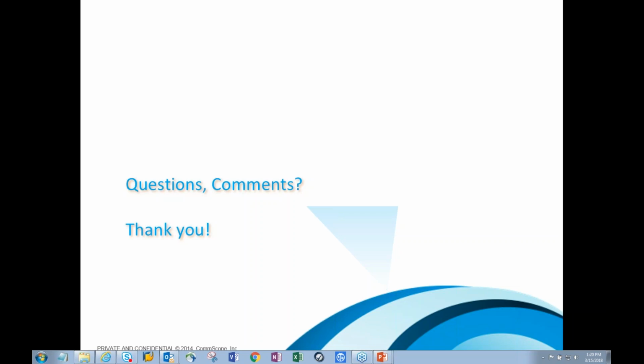Right. And the neat thing about this is you don't have to necessarily do a lot of cable engineering back into the network to make sure that your return levels on your devices are okay, because the micronode is at the home. Exactly. You're only going, in most cases, probably 100 feet or less, so there's no need for that. And that's kind of the beauty of these